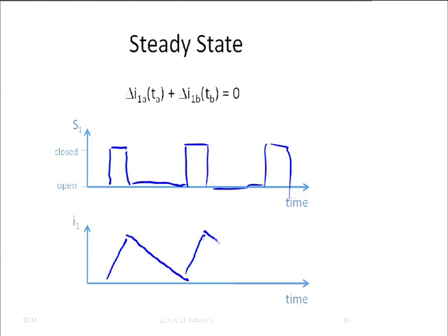How are we going to set the voltage V out? Well, we said we want it to be 10 volts, but why is it 10 volts? If we make this time here longer, is the voltage V out going to increase or decrease? Then it's going to decrease, right? And if we make this shorter, then the voltage V out is going to increase. So apparently, the voltage V out is set by the ratio of T1 and T2, by the ratio of these two numbers.